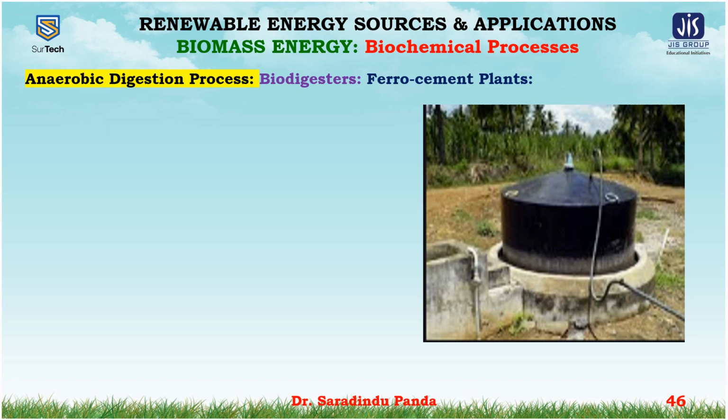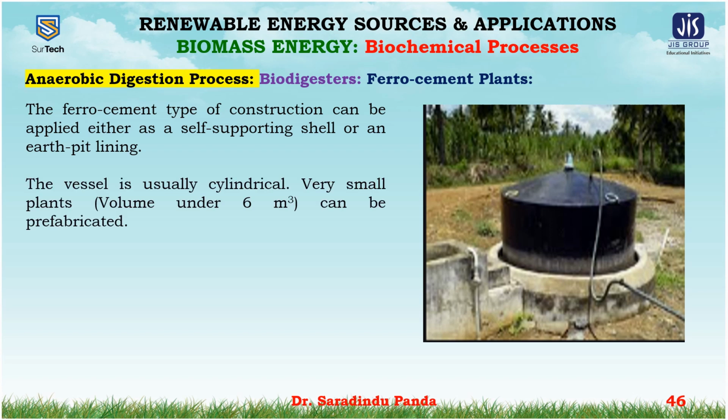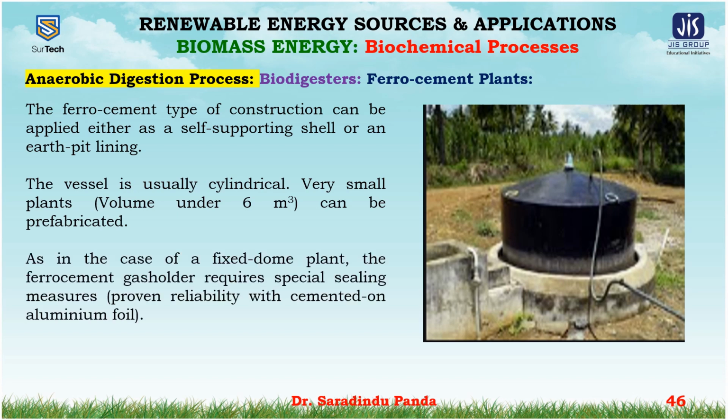The last one is the ferrocement plants. The ferrocement type of construction can be applied either as a self-supporting shell or an earth pit lining. The vessel is usually cylindrical. Very small plants can be prefabricated. As in the case of a fixed dome plant, the ferrocement gas holder requires special sealing measures, with proven reliability with cemented-on aluminium.